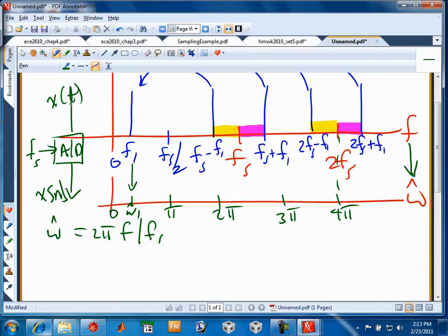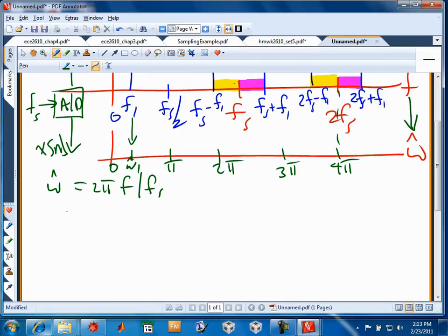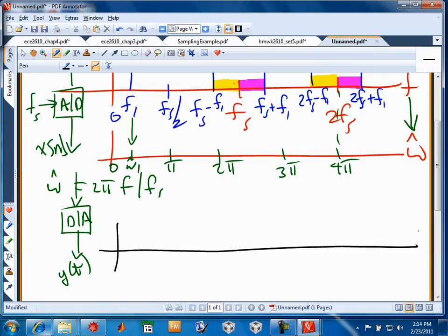And that sequence will have a line spectra on the omega hat axis. So the frequency that comes in at F1 will be at omega hat 1 on the omega hat frequency axis. And then if we were to go to the next level and convert it back to the analog domain using a digital to analog converter, so we'd go back to, let's just call it y of t, then we could go over and again do a spectral plot. Frequency axis in hertz.